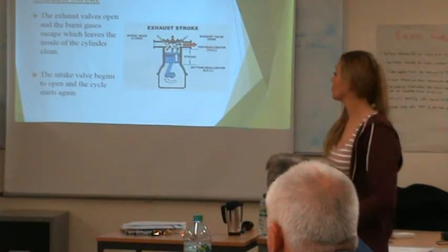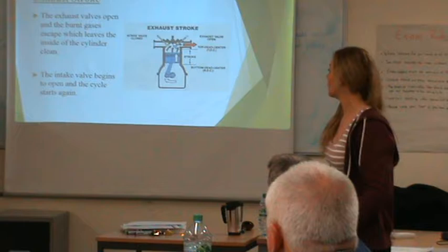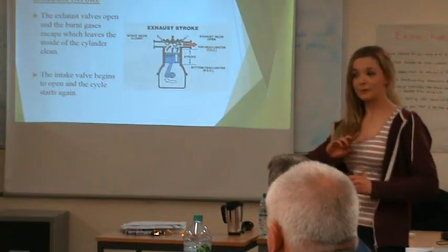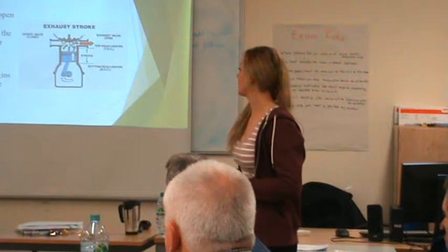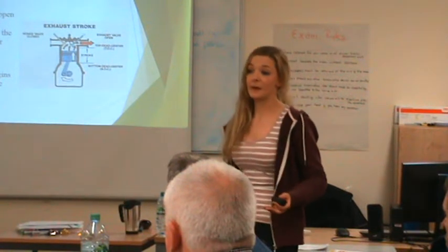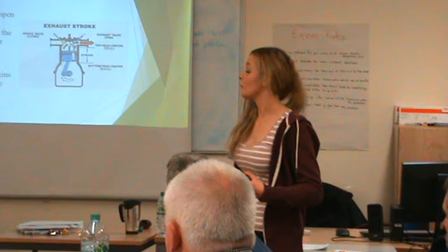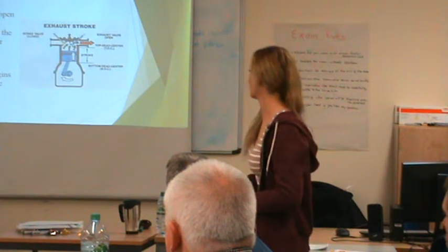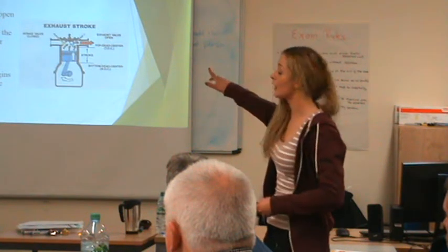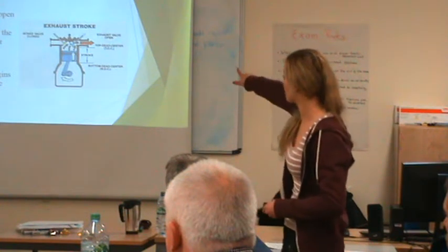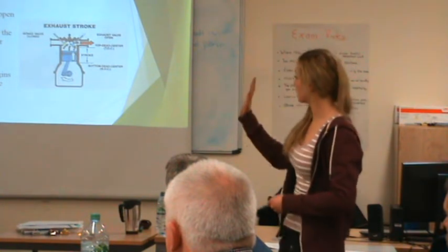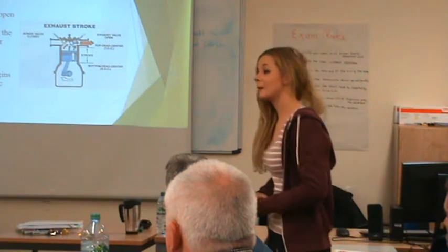And the last stroke is going to be your exhaust stroke. The exhaust valve is open and the burnt gases are going to escape out the exhaust valve and clean out the inside of the cylinder, and the whole cycle starts again because the intake valve will start opening again. If you look at the picture there now, your intake valve is actually closed at that specific time and your exhaust valve on the right is open and the gases are going out. Do you understand? Yes.